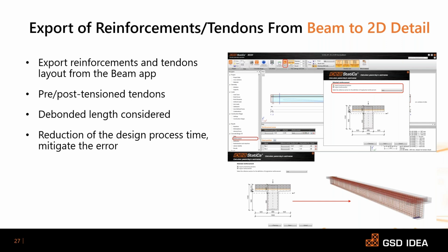So in IDEA StatiCa Beam, users can solve the complex pre-stressing beam task, including the time-dependent analysis (TDA) and also the lateral torsional buckling (LTB). Now they can do these analyses in the Beam application and import it to IDEA StatiCa Detail 2D, where they can account for the discontinuity regions, such as openings, dapped ends, without the need to remodel the beam again or to reload the beam from scratch. Let's see how it works.